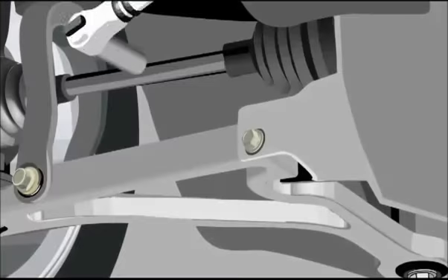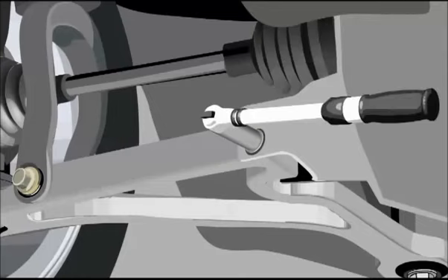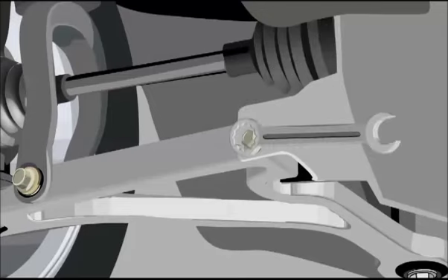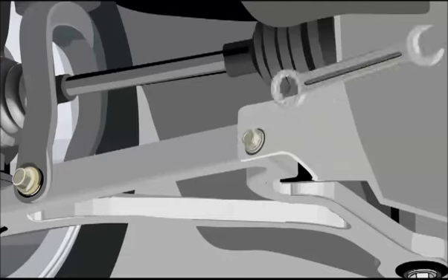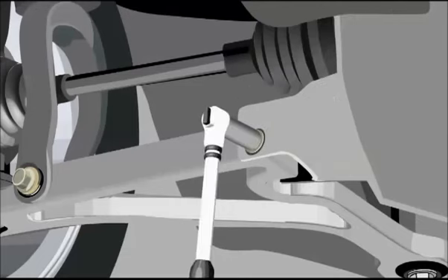When torquing fasteners, there are a few things you need to remember. If you're torquing a fastener and you immediately reach the desired torque, it may already be over-tightened. Loosen the fastener with a tool other than the torque wrench and re-torque it. Final torque must be reached while the fastener is still turning. If the fastener stops moving before it is fully seated against the clamping surface, it must be loosened and re-torqued. The fastener may be binding, cross-threaded, or have dirt in the threads.